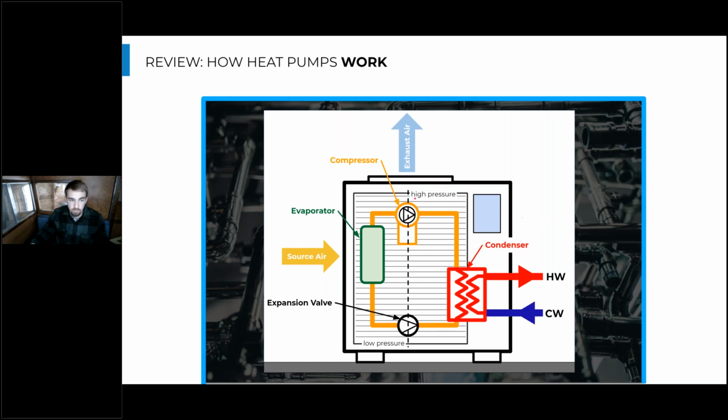Yeah, they definitely are. In several different heat pumps, they will change the speed of the compressor depending on the conditions they're in, to only flow the amount of refrigerant necessary to transfer the heat that's available. Explaining it in terms of changing the compressor speed might be diving into the weeds a little bit, but yes, they do operate.